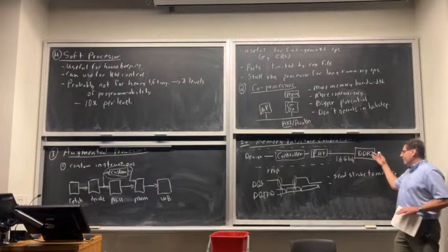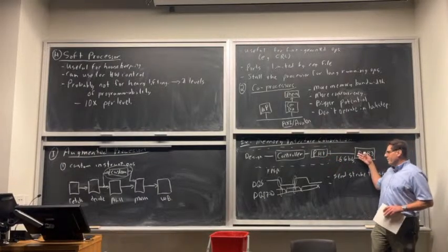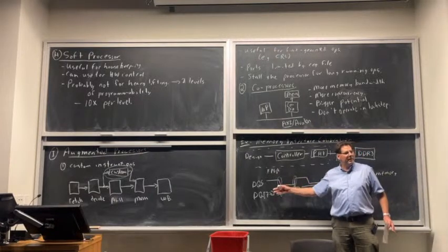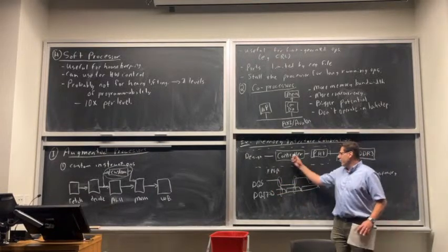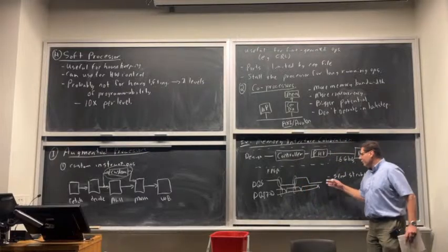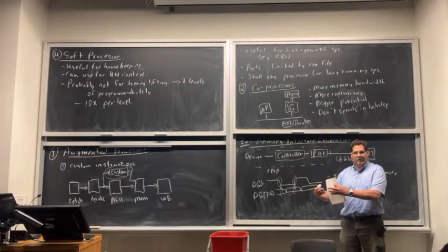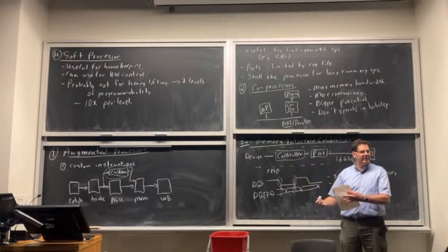And this actually also happens in reverse, okay? So when we're doing a read from the memory, it sends back a strobe, and it sends the data, and the FPGA will use that strobe to sample the data. So it's called source synchronous, because whoever is sourcing the data doesn't just send the data, they send alongside it a strobe that you can use to capture it. Does that make sense?